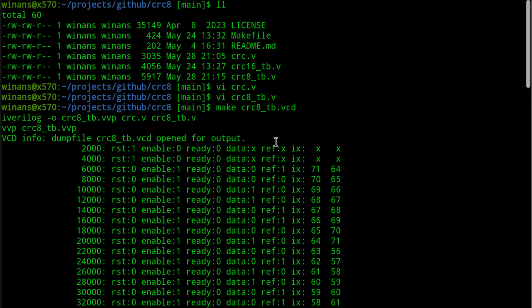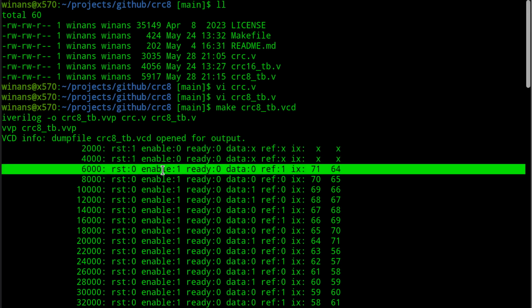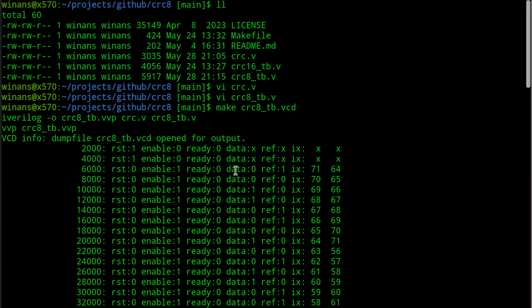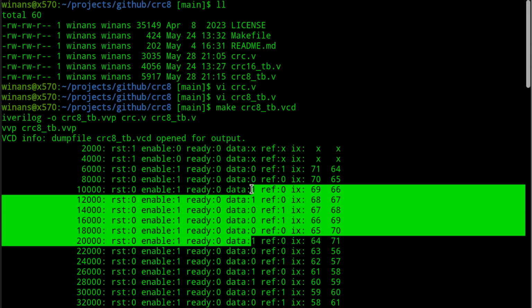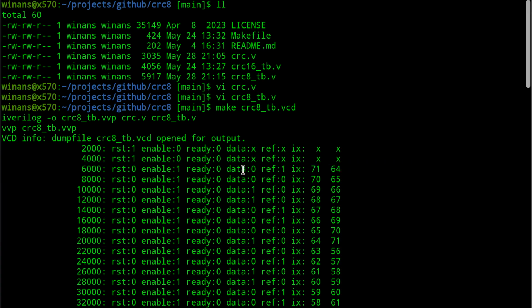Look what happens in the data bits one at a time that are going out. You can see the reset's true here. The enable then goes true here. So this is the first bit that's sent into it. And in most significant bit order, remember it starts with an ASCII 1, which I said was a 31. That's 0011 0001. This in ASCII, in big endian binary first, that's your 31.